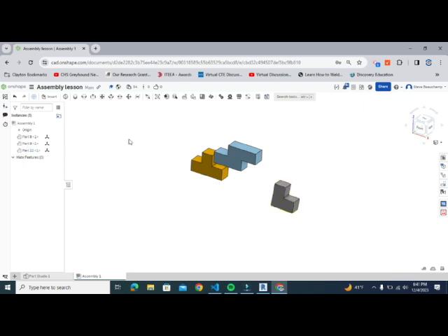Okay, and that's the idea with the assembly. By taking 2 parts and putting them together, in essence what we're doing is we're removing degrees of freedom. And we have a whole bunch of different mates up here. We have a fasten mate, a revolute, a slider, a planar, cylindrical, pin slot, ball, parallel, and tangent mates. And all of those remove certain degrees of freedom.